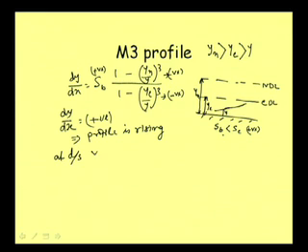At downstream, y is approximately equal to yc, and when y is approximately equal to yc, we know that this ratio yc by y becomes 1, and then 1 minus something which is also equal to 1, so the denominator becomes 0. So, when this becomes 0, the ratio dy by dx becomes infinity.